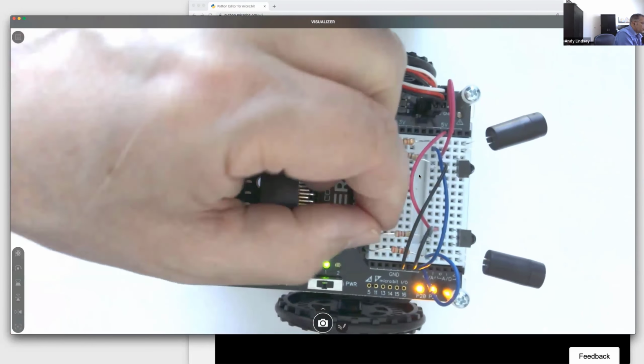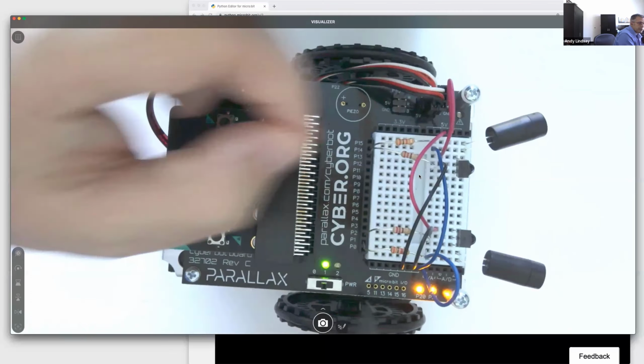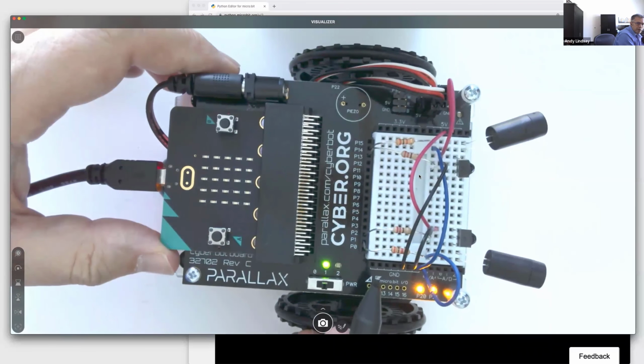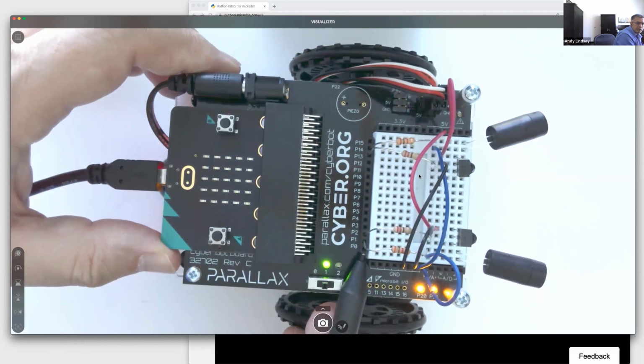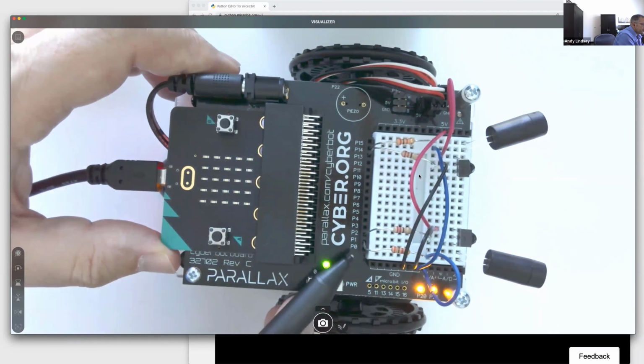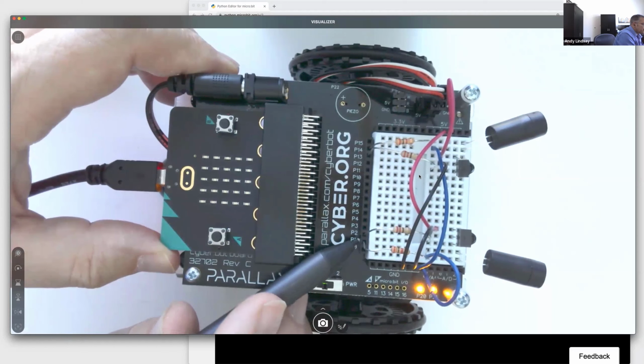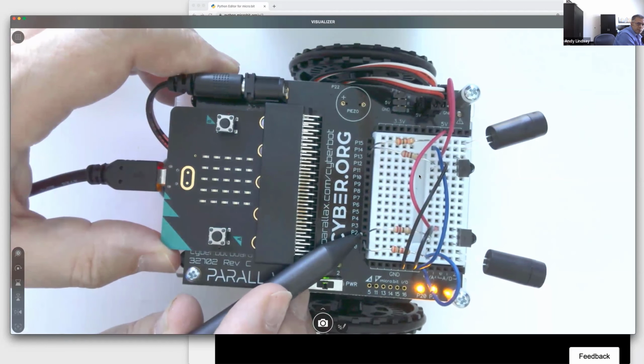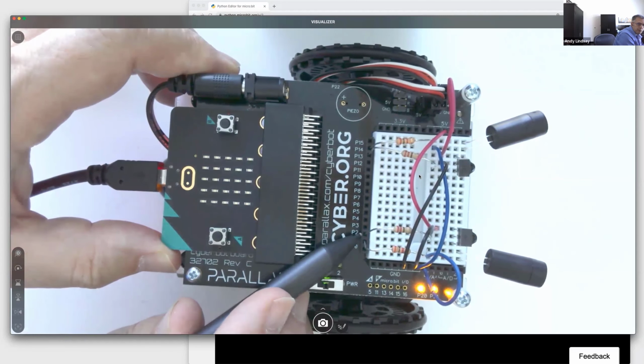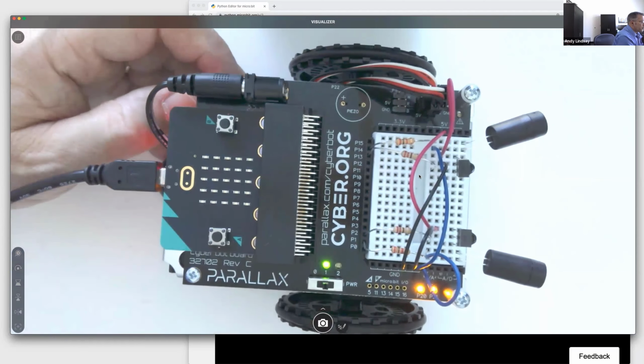What I would do is go through, first of all, make sure that no wires are touching each other. Make sure that you've got one empty socket down below here, and then your red, black, red resistor is going to plug into P1. And then your red, red, brown resistor should plug into P2. Double check those.